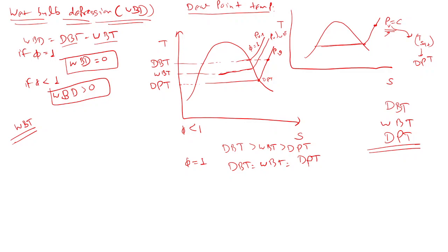And the final temperature is also the same? No, sir. The final temperature is reduced. So one thing we can say is that H total would be constant, right? In the psychrometric chart, a constant enthalpy line is there. So we follow that constant enthalpy line.